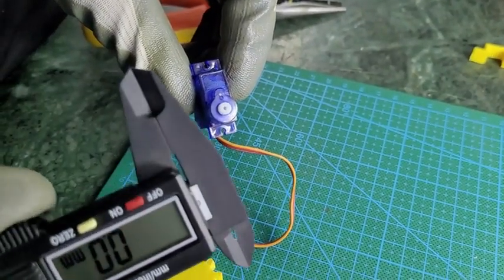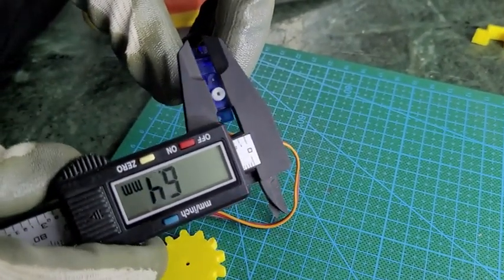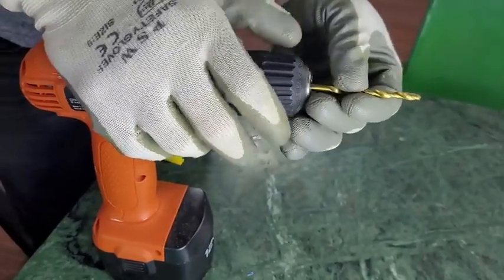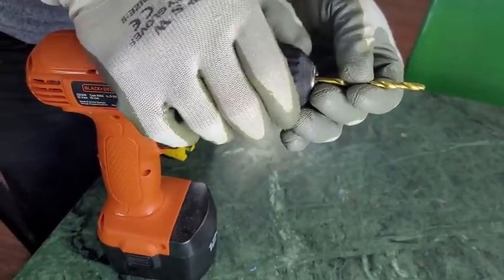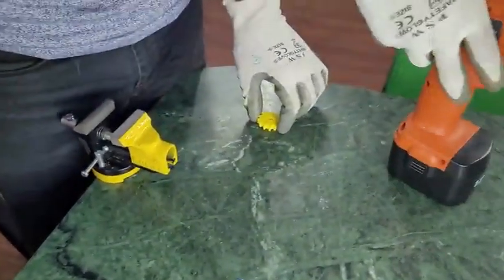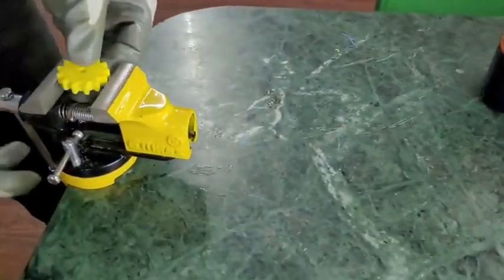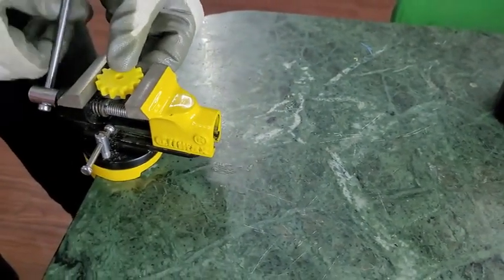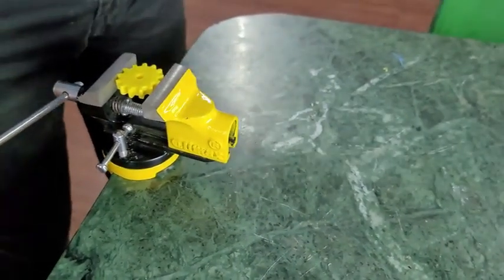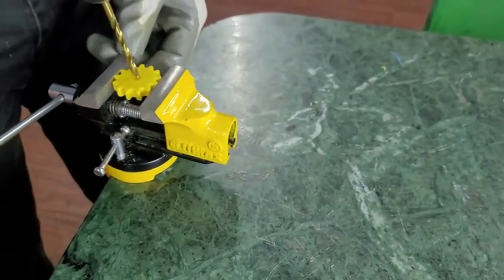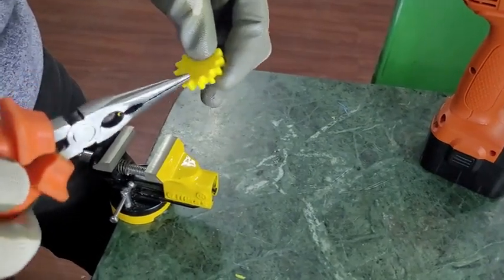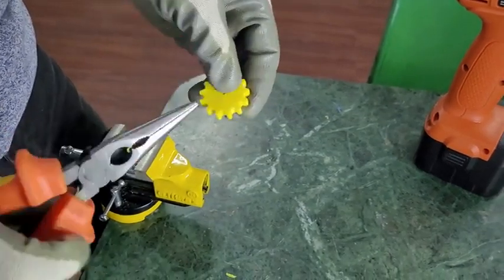So measure the shaft diameter of the servo motor, which is 4.8 millimeters. We need to have the right hole size on the gear. So let's take approximately a 4.5 mm diameter drill, put that into the drilling machine, hold the gear that we 3D printed onto the bench vise, tighten it securely so that it doesn't slip, and then make the drill at the center. There is already a 3D printed hole,